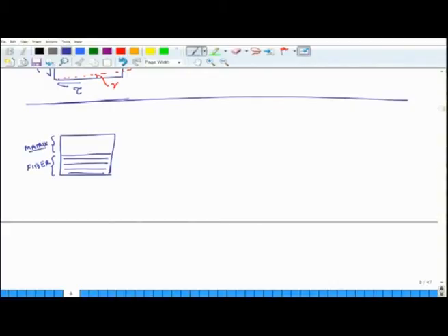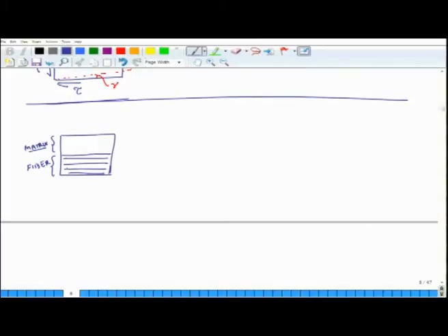So, in reality the fibers and matrix are all uniformly distributed, but just for purposes of our understanding, I am lumping fiber at the bottom portion and matrix in the top portion. And this kind of lumping is valid because in reality the behavior of this system for shear will be fairly close to the actual system, and why, that is something we will discuss later.